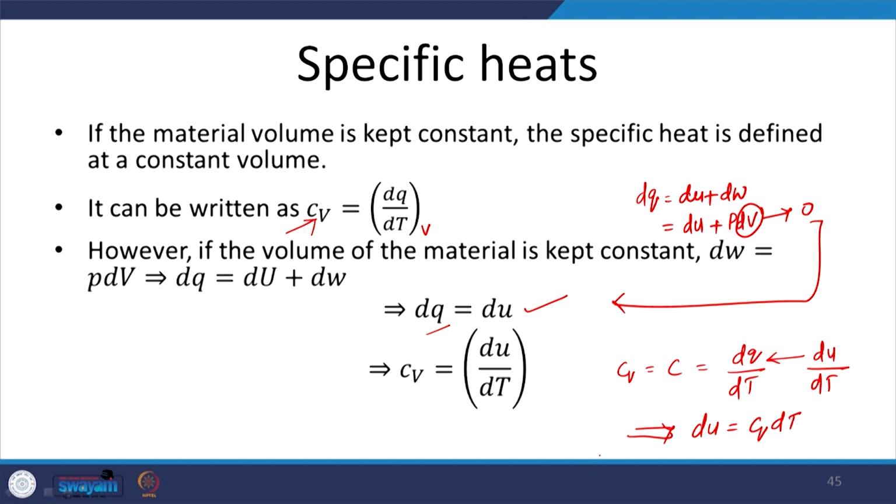For our discussion, we define the specific heat as the ratio of the change in internal energy, as a result of the additional input of heat, to the change in temperature at constant volume, right. So, Cv can as well be written in its own definition, dq by dT, but since it is a process at constant volume, this is equivalent to this.